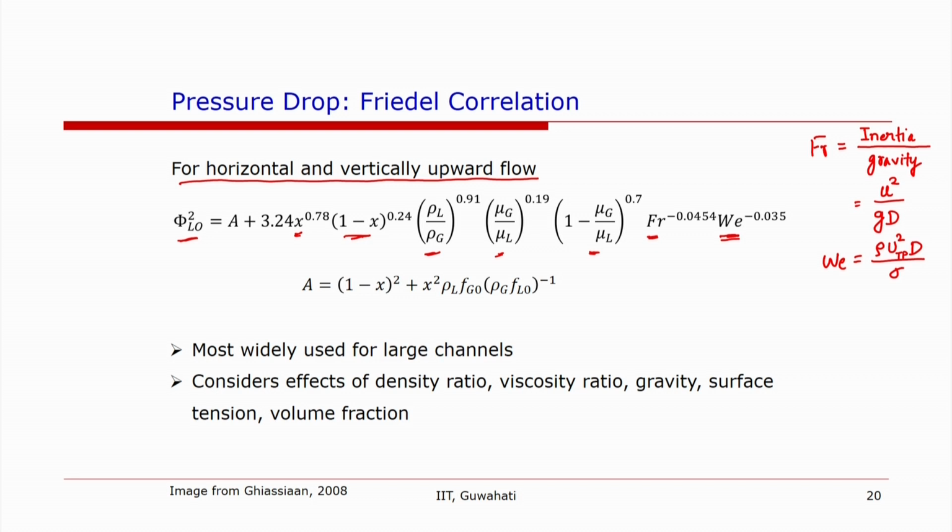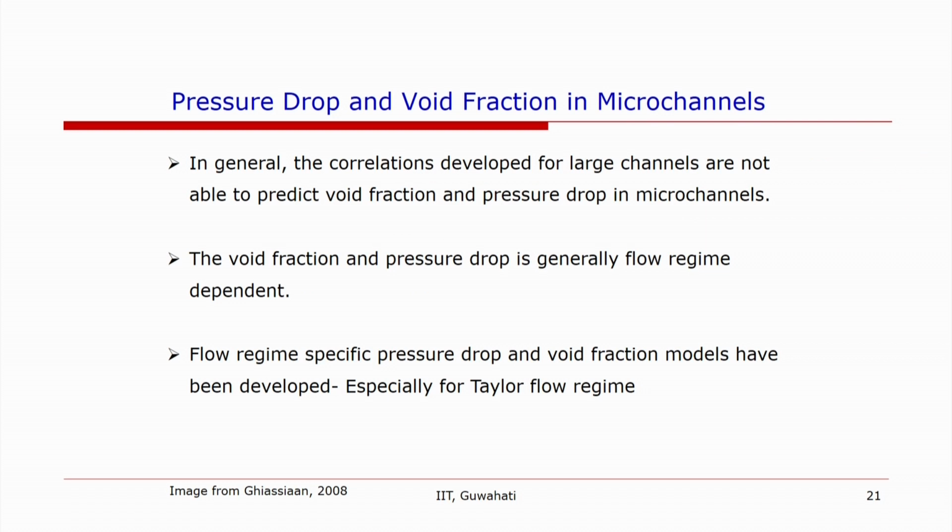And this might be a good idea to check the validity of Friedel's correlation for microchannels, which has been done by some researchers. Okay. So in general, the correlations that have been developed for large channels are not able to predict void fraction and pressure drop in microchannels as they are. Some modifications have been suggested.